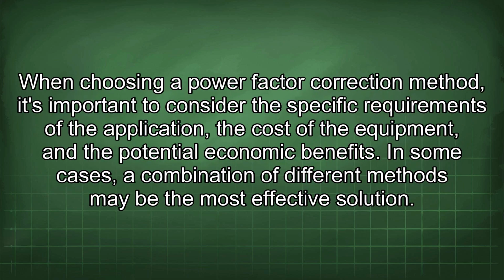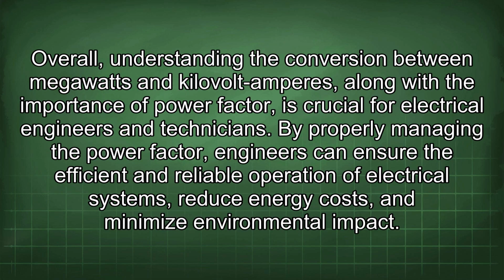When choosing a power factor correction method, it's important to consider the specific requirements of the application, the cost of the equipment, and the potential economic benefits. In some cases, a combination of different methods may be the most effective solution. Overall, understanding the conversion between megawatts and kilovolt-amperes, along with the importance of power factor, is crucial for electrical engineers